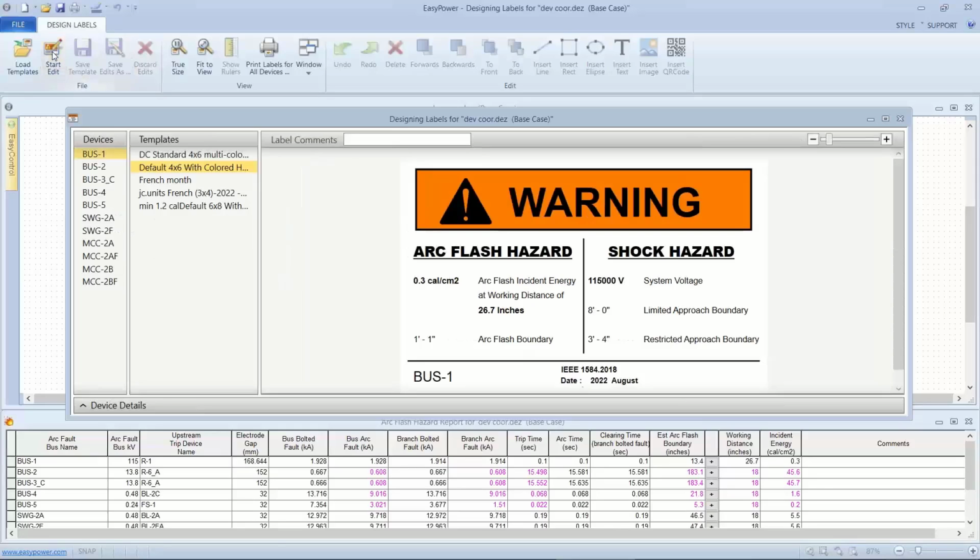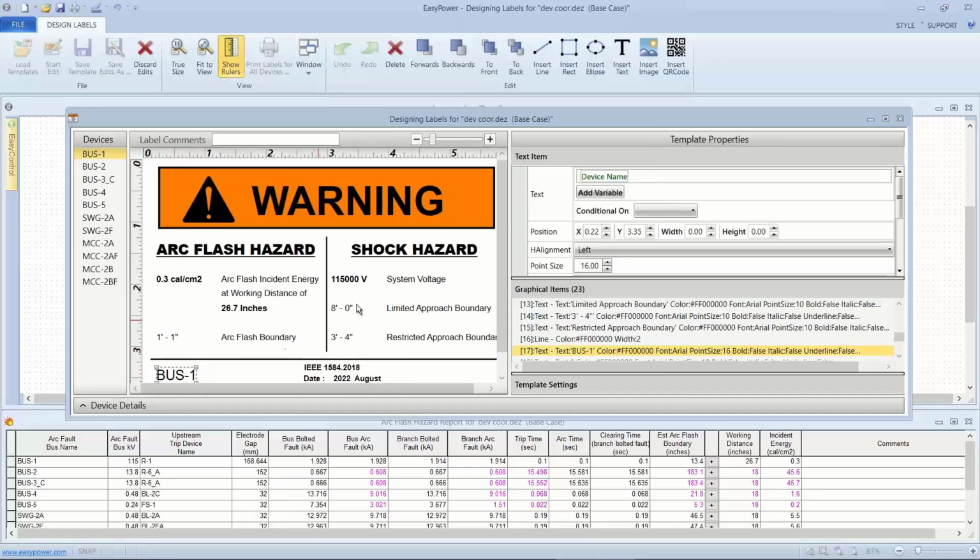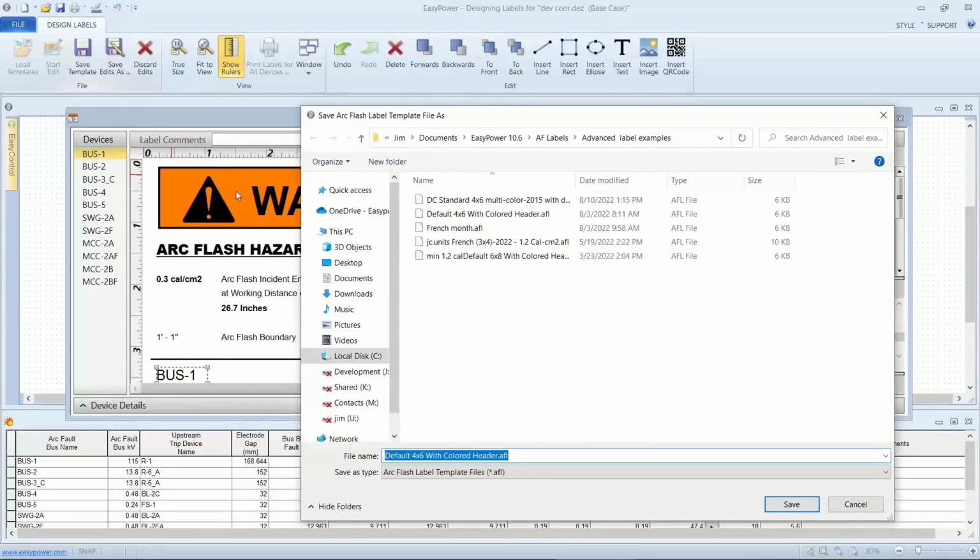I start the editor, and I'm just going to put a blank into one of these spaces just to make a difference. So here under the device name, I'm going to put 2 extra spaces, and as I do, this allows me to save the edit as a new name. So I'm going to save as up here on the top left, put in the name 01 default.